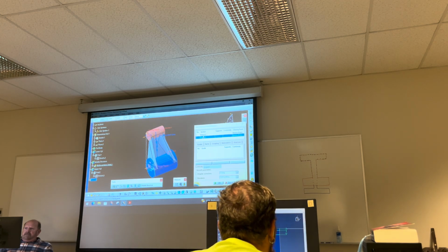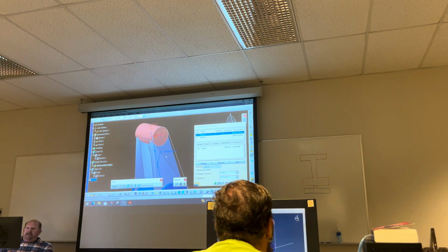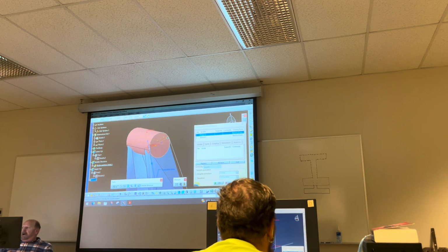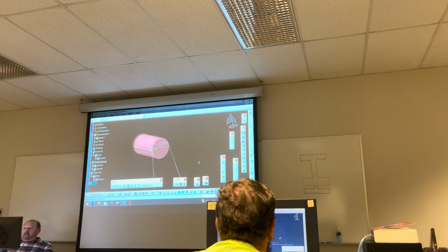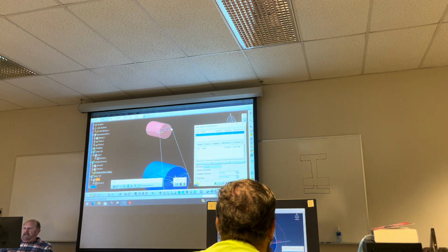Now I'm going to double click sketch 5, and it says select a support surface or modify the current section. Well, I'm back up in here. I'm going to pick this corner and see if it'll let me change a closing point. See, I'm already out of that realm of editing. So I'm going to cancel this. That's why I said it's very important when you're in there to do your editing of the sketch.